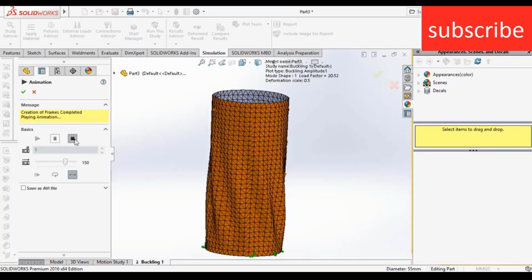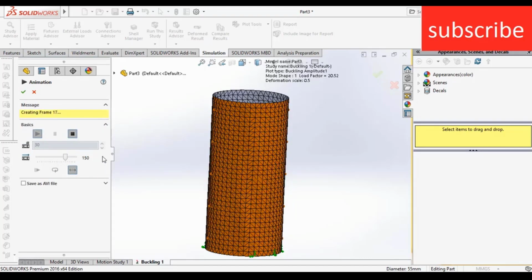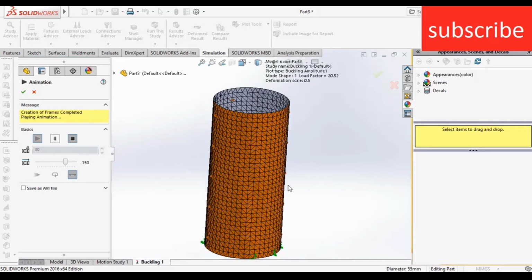First thing you need to do is click on stop. Now here is basically the frame rate. So here it is basically 5 frames per second. To increase the frame rate, just enter the value, for example 30. Click on play. The first thing it's going to do is calculate all the frames. Here you see it is calculating. Now it's 30 frames. Now it can show you the animation.